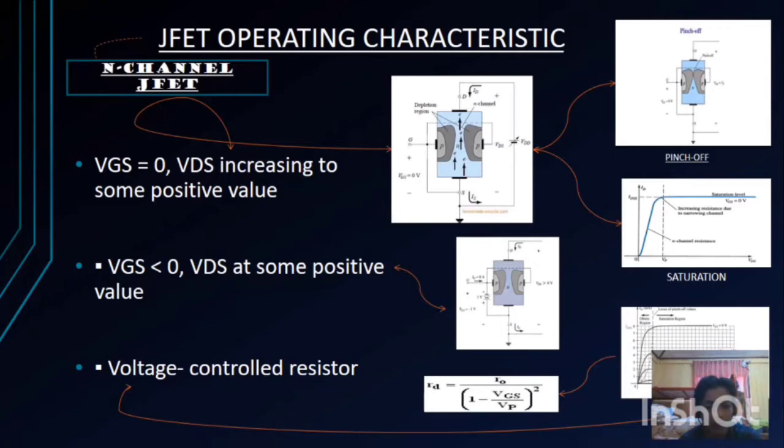In this case of VGS equal to 0, where VDS increases to some positive value, we have pinch off and saturation. For pinch off, if VGS equals 0 and VDS is further increased to a more positive voltage, then